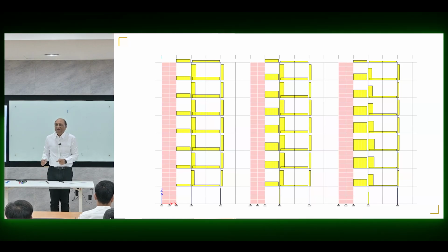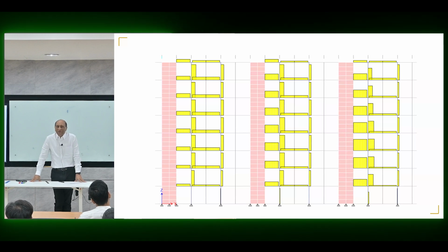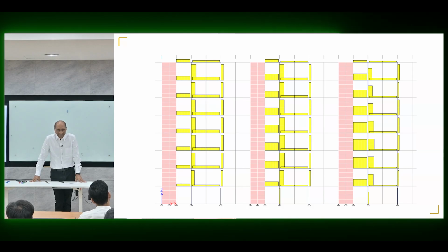So you will never have a shear failure because moment will yield first, and yielding of moment is not a problem because that's perfectly fine. Ductility, we studied about ductility so much. We have ductility of 8. So no problem with ductility. You let it yield. That's why the ductility is there, to let that yield and not be damaged.